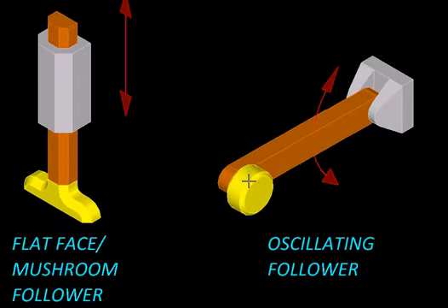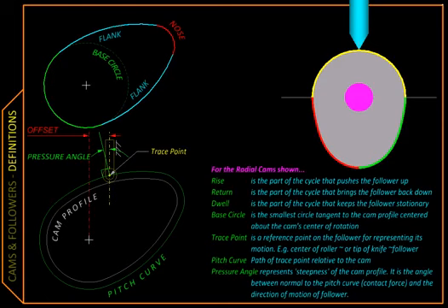Let us now see some of the basic definitions associated with cams and followers using a simple cam. A simple cam is usually a metal plate with a simple profile primarily made up of just straight lines and circular arcs. The purpose here is simplicity of fabrication and not the precision of a function that governs displacement against time. So we are just interested in raising the follower through a certain height, maybe holding it up there for a while and bringing it back. We are not necessarily concerned about how it reaches that height.